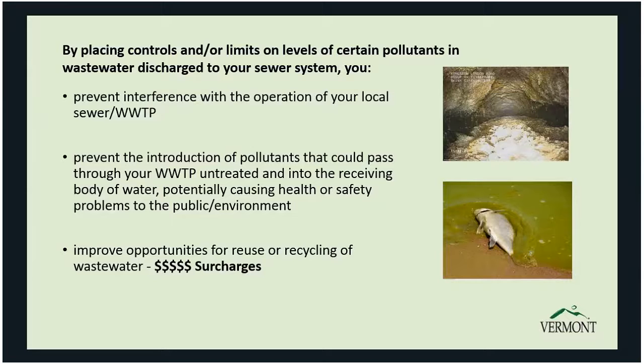Typically, wastewater treatment plants or towns will require surcharges for businesses who are discharging high levels of high-strength waste, and that's usually based on their BOD. So it's also good business and can save money.